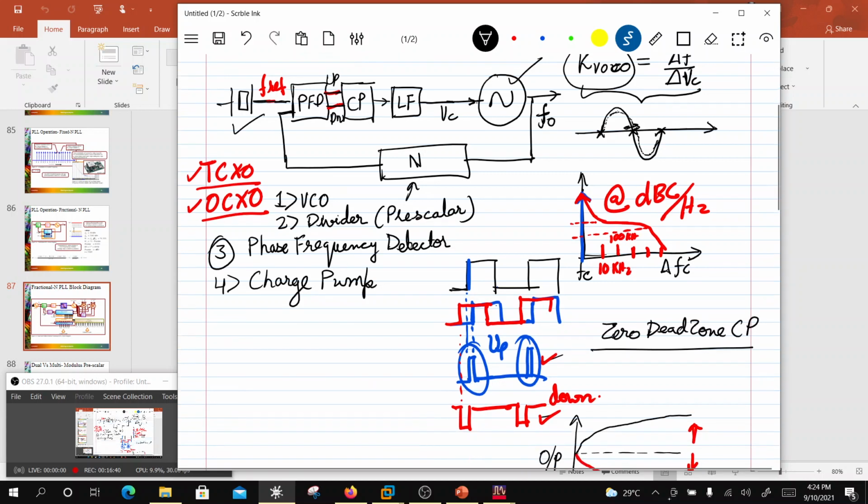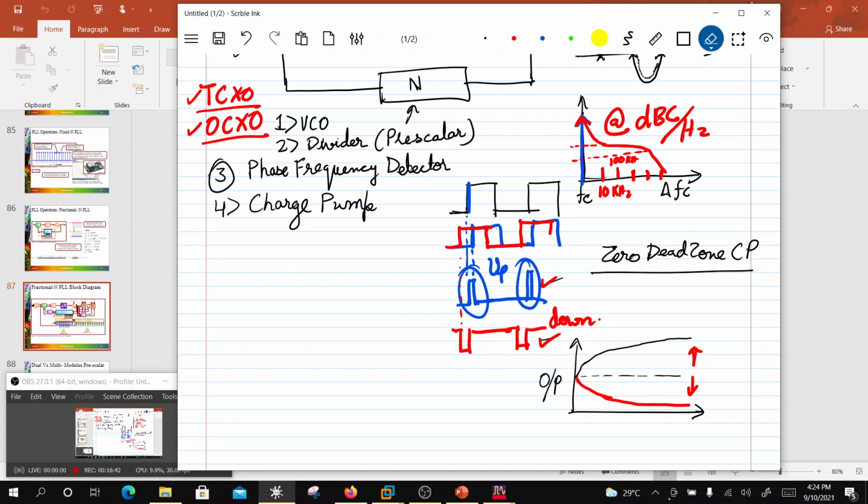So what's going to happen is, if I was to draw in the same diagram, I can show you what happens to the phase noise. A free running VCO would have a higher phase noise and then it rolls off like this. But as soon as you put in a loop filter, then in this loop bandwidth, this is going to follow the crystal.